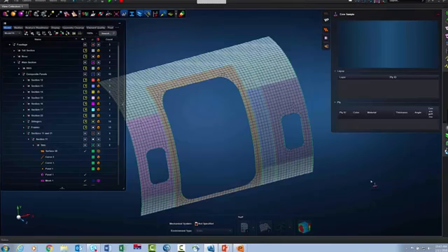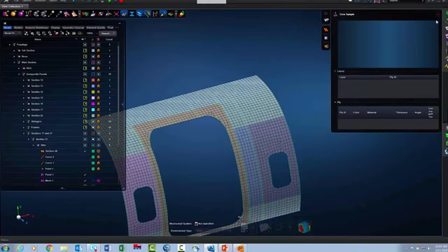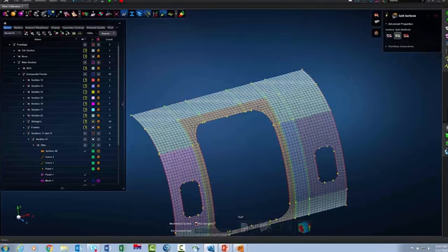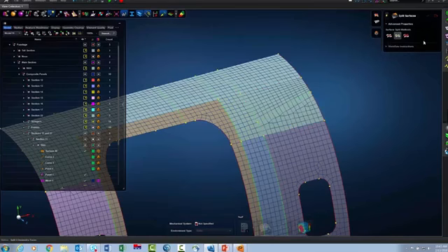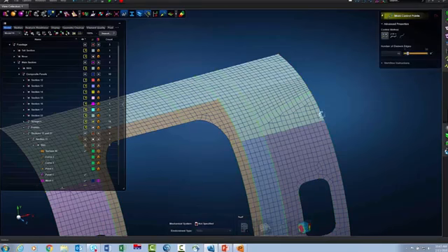Let's go back to the core sample tool, and I want us to note this area here that only has the 2 plies on it. Okay? And let's make some changes that will affect that area. So the first change we're going to make is we're going to split the surface. Maybe I need to split the surface because I need to do some manipulation of the mesh in order to better capture some results. As a matter of fact, maybe one of the changes that I might make is a change to a mesh seed, okay, a change to a mesh seed.